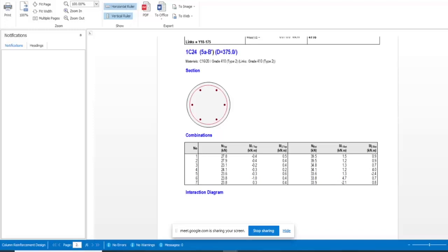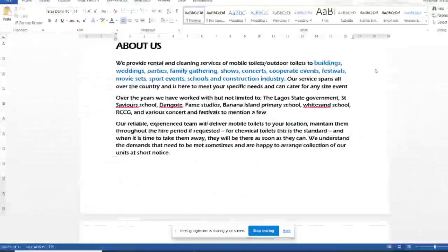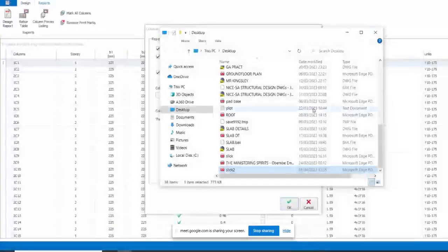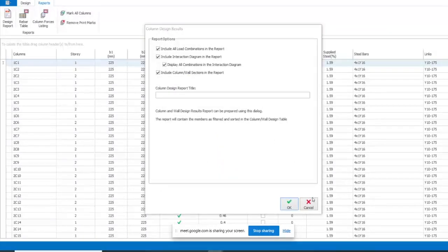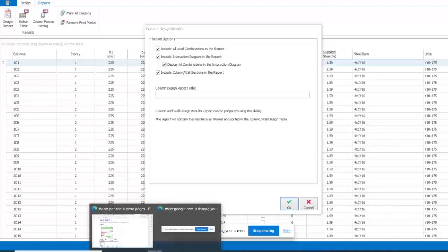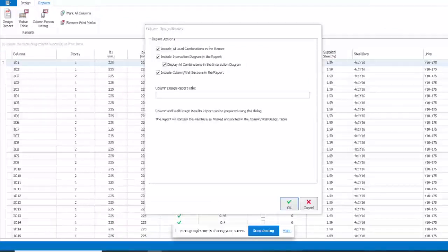Do I have any of my private students here? Let me check now, because if they are here, 0.13 or 0.24 percent. Can you give me a distinction? Where's the difference coming from? One is for high yield and one is for mild steel. Which one is which? I can't really differentiate now, but I know it's 0.13 and 0.24. That's very good. 0.13 is for high yield, 0.24 is for mild steel.